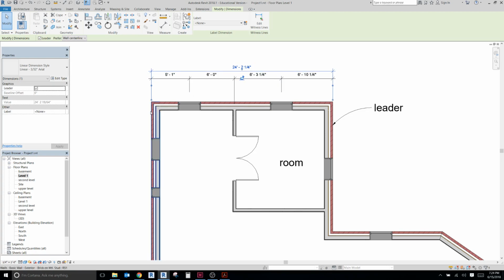And that means that when you dimension something, like from this wall to that wall, you have the ability to take that dimension and lock it when you're finished. And what that means is that if somebody tries to move or delete one of these walls, they're notified that there is a locked constraint, and that by moving or deleting or otherwise altering, that will be destroyed.